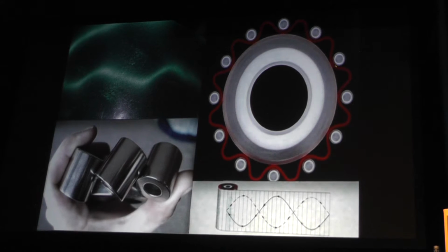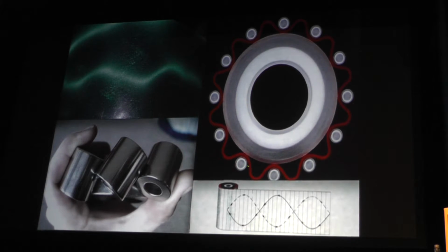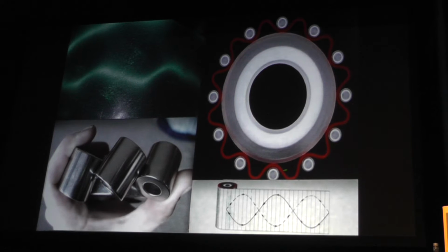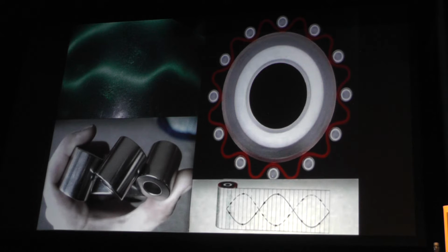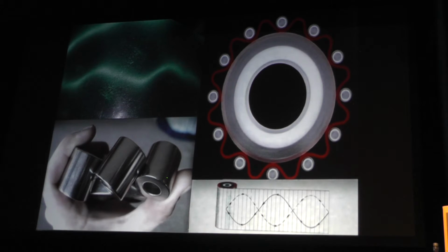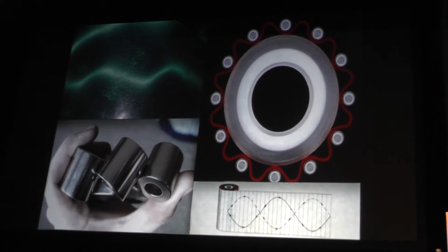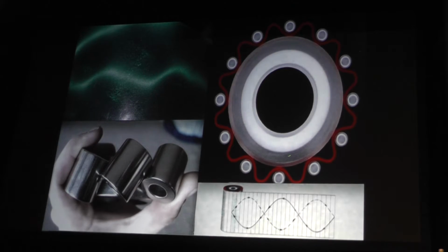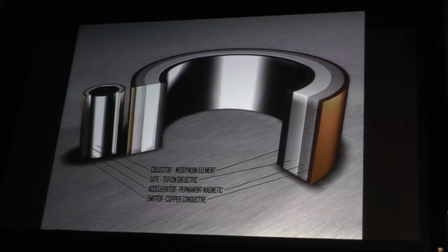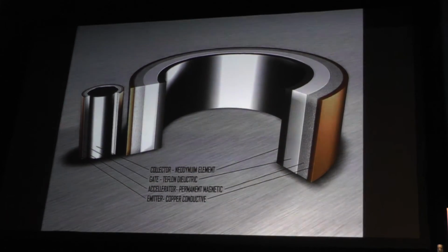So these rollers or runners are carried along in the troughs of this wave, which runs all around. When you bring a rotor or a rotor magnet set, and they're made up of normally 8 stacked discs, the runners are carried along in the troughs of these sine waves, like an Archimedes water screw.